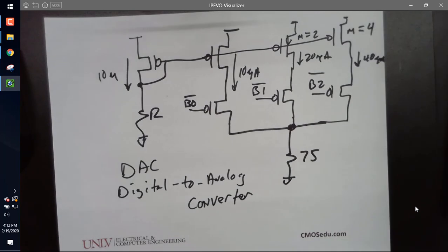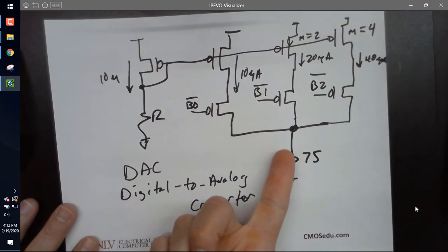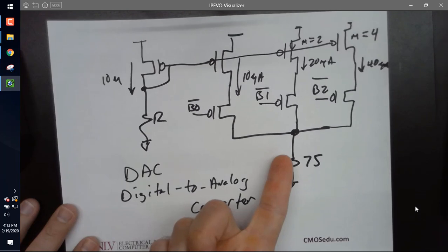We all follow. So now imagine we're using this DAC, and for whatever reason, the power supply drops a little bit. What's going to happen to my currents then, my 10, 20, and 40 microamps? They're going to go down. What's going to happen to the intensity of the signal in my monitor? Go down.